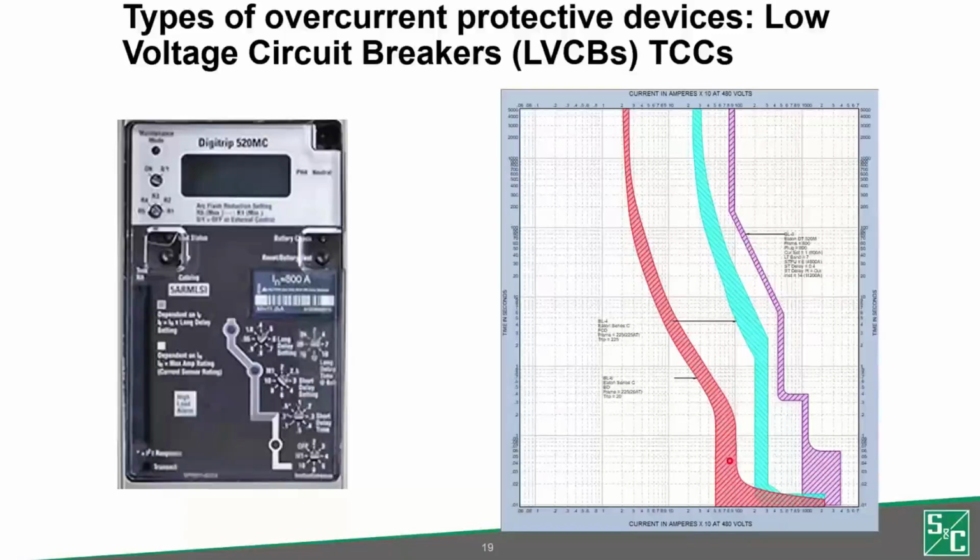Whereas the magnetic setting for breakers has an instantaneous response beyond the setting given for the magnetic element. And while the thermal response is usually fixed based on the current rating of the breaker, in some cases, the magnetic setting may or may not be settable based on the make and the type of the trip unit.